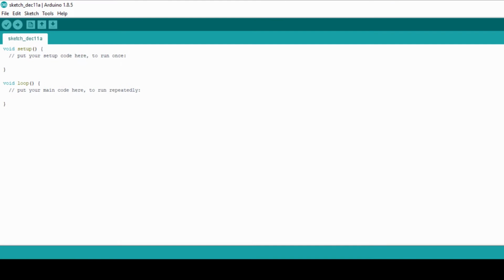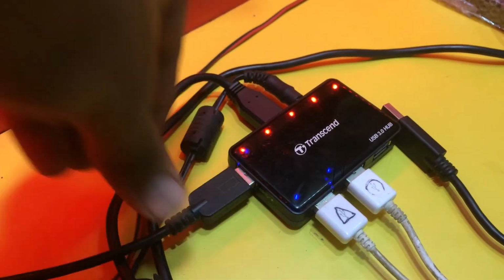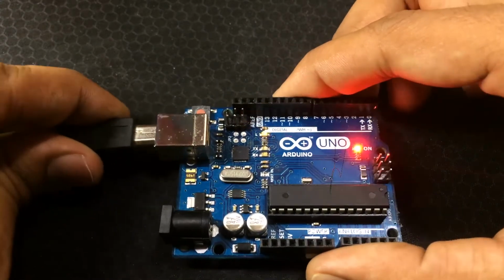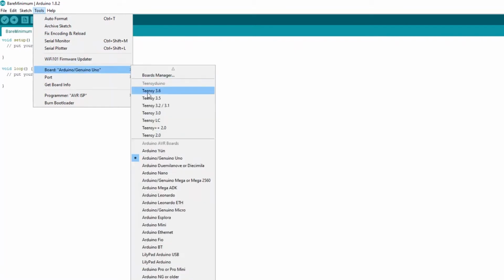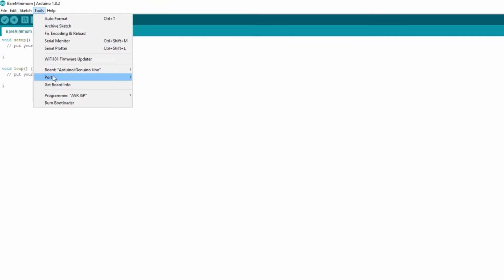Finally, now that we are in the IDE, let's program an Arduino. First, let's connect the Arduino to our computer and verify the following things in the IDE. Click on the Tools menu in the toolbar and check if the right device is selected. Just below that, we have the option for ports. This decides the port to which our Arduino is connected, so all the code we compile is uploaded through it.